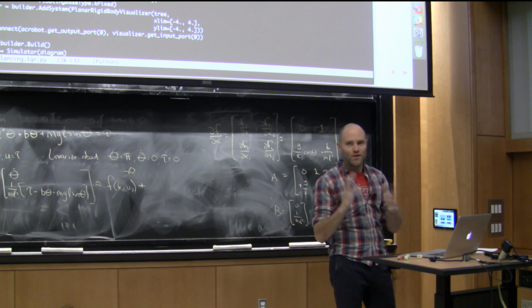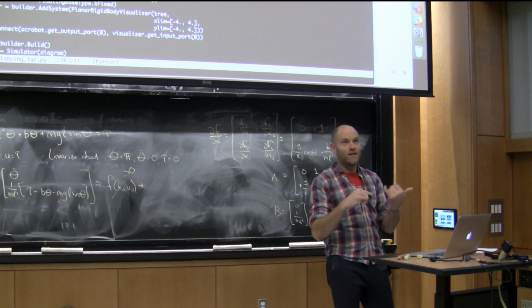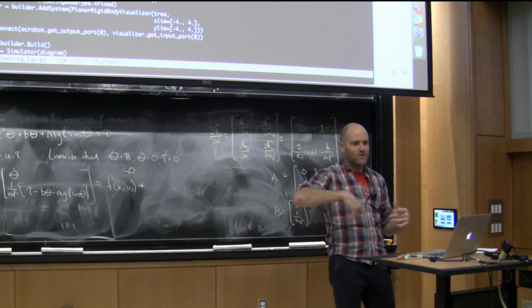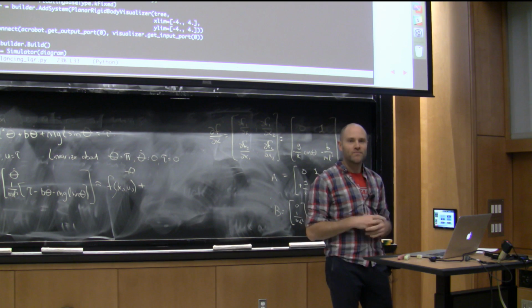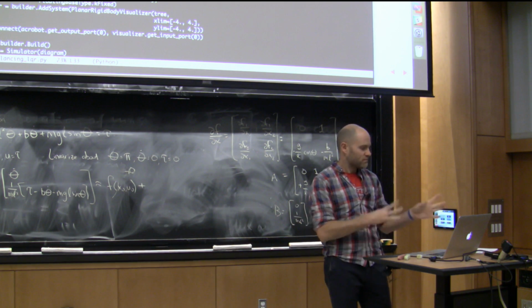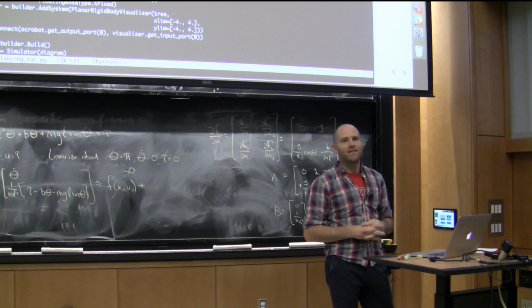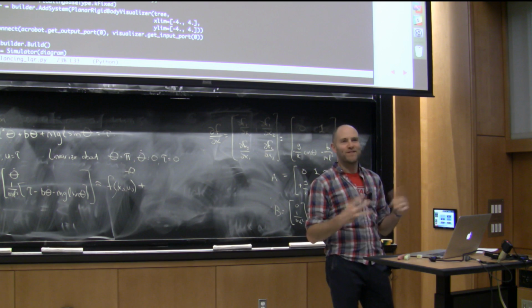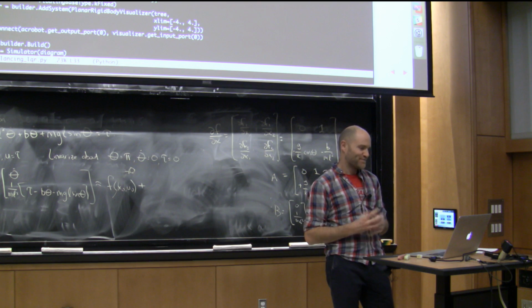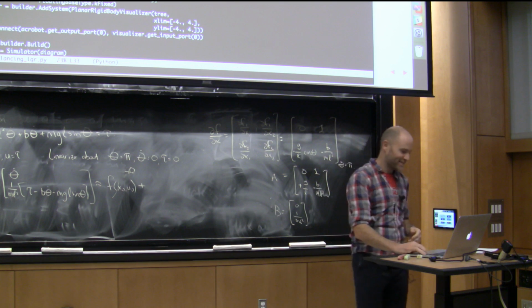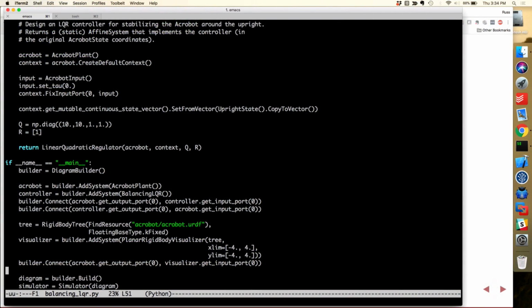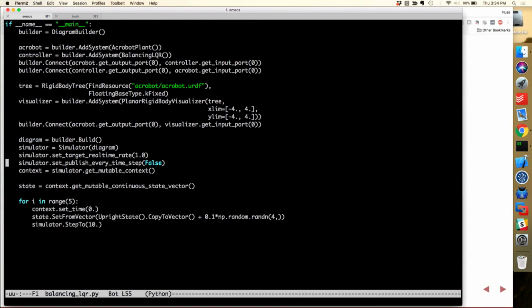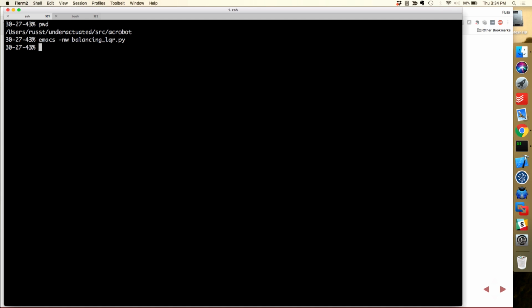And the natural conversion of radians to radians per second for a pendulum type thing would be using the characteristic time constant of the pendulum. And if you always divide by 10, you're pretty good. It works for quadrotors too, and they're not meter long. Although Peng's built one that's bigger than that. Okay, so then you call LQR on it, and it kicks out a controller that you can just put into your system. And let's see how it does.